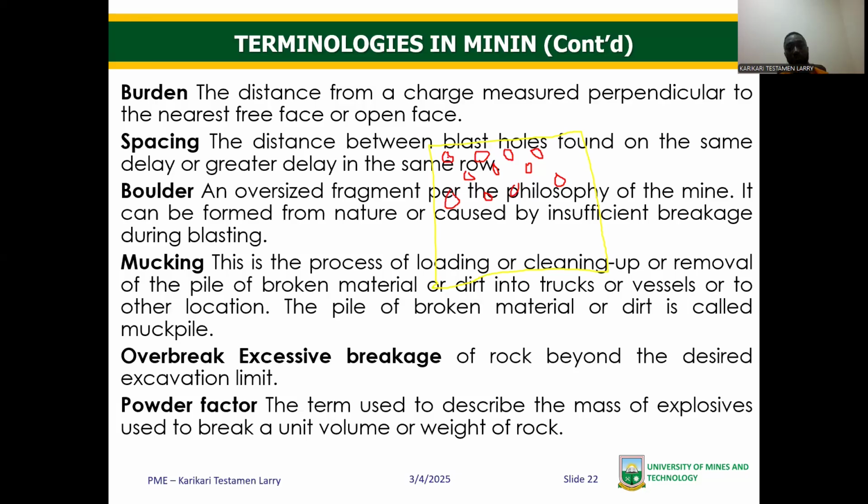This is our blast hole. The distance between this blast hole and this blast hole is what we call burden. You can say that the distance between two blast holes on the same column is burden. But the distance between this and this is what we call spacing.